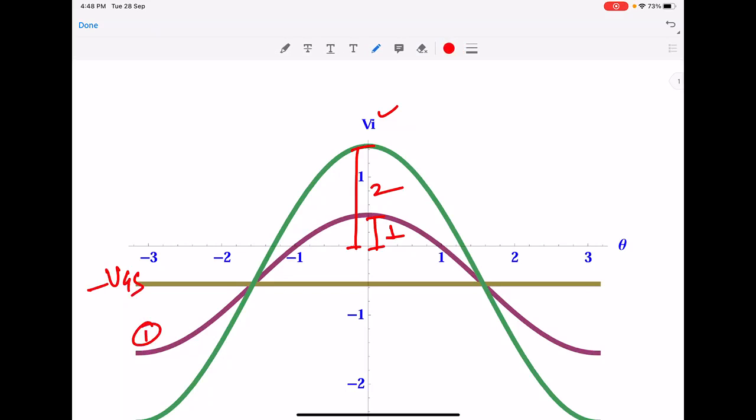So here you can see that what we have is phi was from -1 to 1. So this is 2 phi, minus phi to phi. But when we increase the amplitude and gate to source voltage remains same, so now we see that the total input is non-zero over a wider range compared with the previous case.